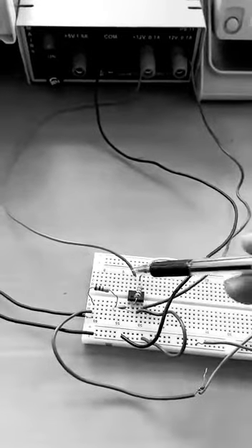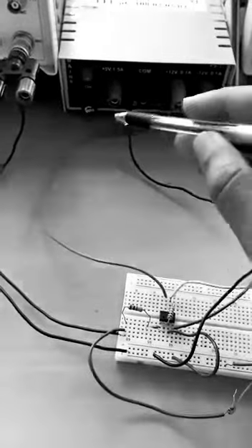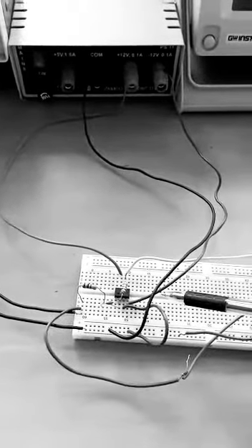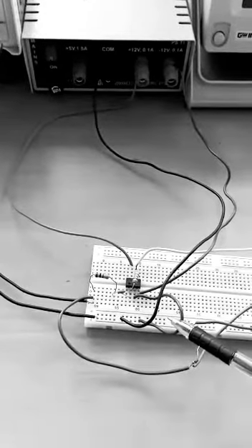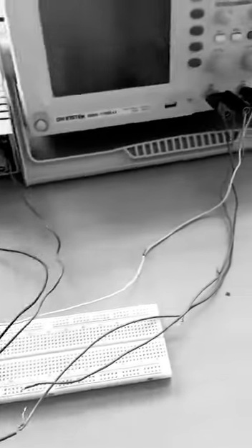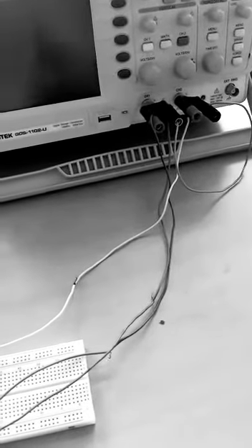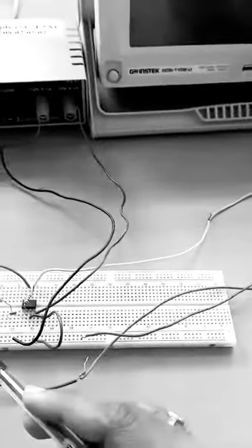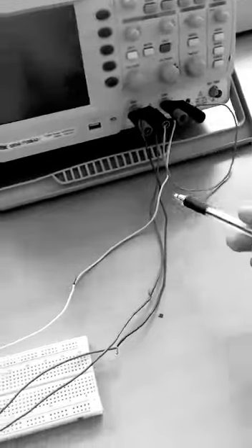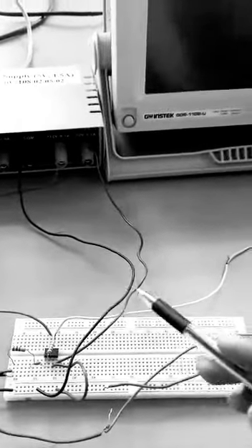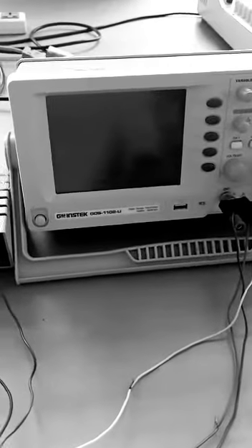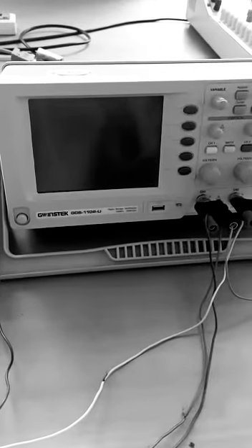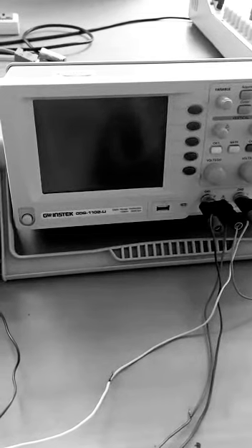Pin number 7 is connected to plus VCC, pin number 4 is connected to minus VEE, and pin number 3 is grounded. From the DSO we have taken 2 wires. One is connected to the input, and the other channel wire is connected to pin number 6, that is the output. So on the DSO screen we will be checking both the waveforms, input and output, at the same time.